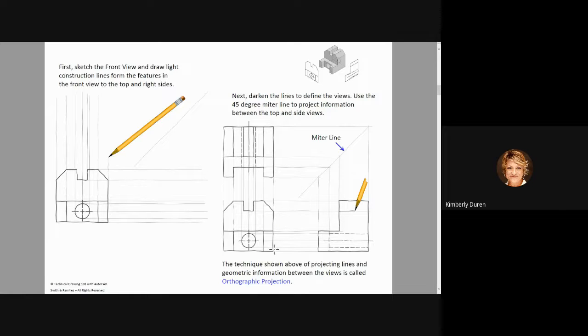And a cool way to do this is to take a ruler and put it down here. And then I come up. Oh, I've got a hole right here. Well, I can project from the southern quadrant or the very bottom apex of this straight over. That's where my hidden line starts for my hole. And then the top extent of that hole.